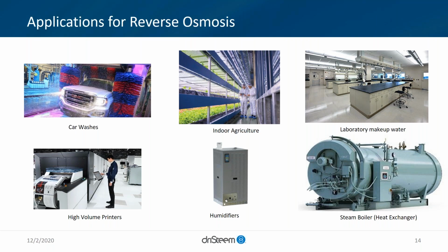Humidifiers, which I assume most in the crowd are familiar with. This really prevents undue maintenance that could be prevented with water treatment and really extends the lifespan of that equipment. The other added benefit is if you have less in the water, you need to drain less frequently, which is true for humidification and steam boilers or other heat exchangers. That's one of the main reasons you're draining it. You've already heated that water up. Why would you want to put it down the drain? Well, it's to protect the equipment. And this is how we can maximize the time between those drains.